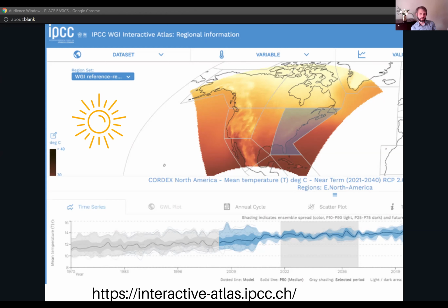So there's a lot of resources out there on people trying to make estimates of the future. One thought is we can assume that the temperature is going to continue to increase, and I have the energy logo there. If you think back to the energy pillar section, we talked about right sizing our heating and cooling equipment. Well, the fact of the matter is we might need to oversize it, in the sense of a modulating system, so that as more extreme temperatures come, both hot and cold, we've got a system that's right sized to run the majority of the time, not overheating or cooling or overrunning, but then thinking through, okay, what's going to happen?